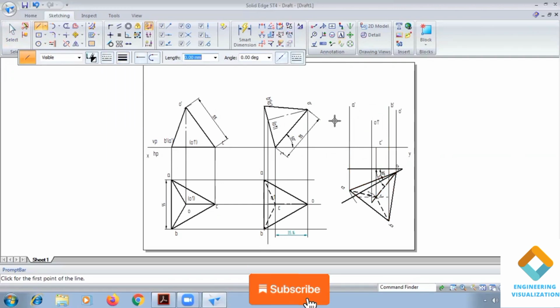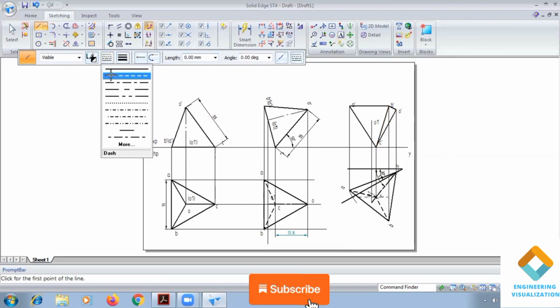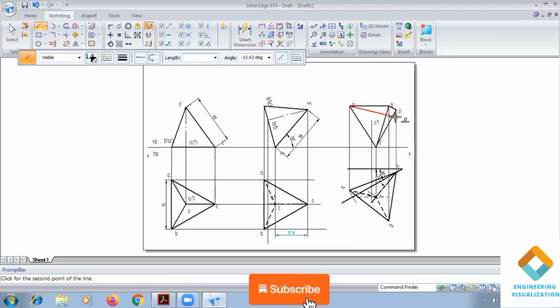Okay, after writing the notations, you can join it first. Join the triangular face and then the slant edges. If any of the slant edges passing inside, that will be dashed line. Passing outside means it is continuous one. So the dashed line from this end to here. Okay, and then finally we need to draw an axis. Okay, that completes the problem.